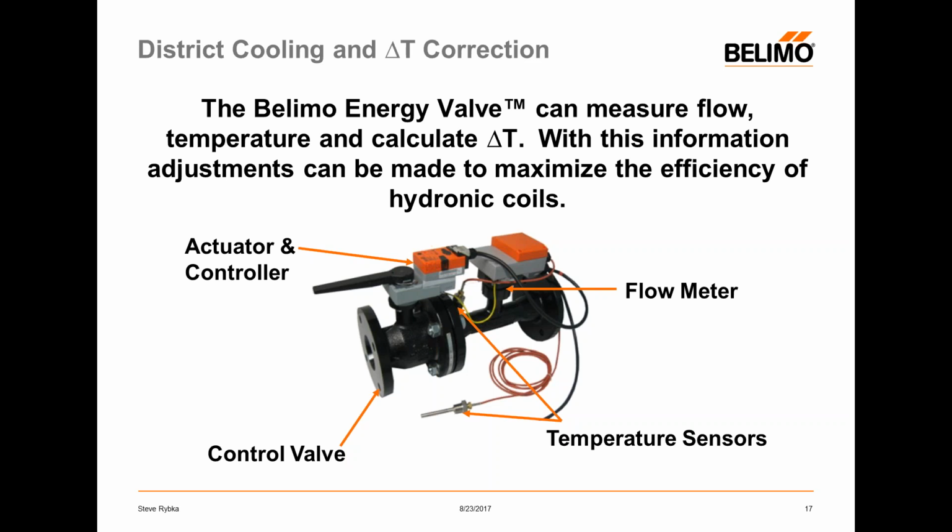So Belimo's been known over the years to make some pretty smart actuators, and we've leveraged that technology to build this thing called the energy valve. And what we can do, again, is measure those flows, measure that temperature, and if we get off our design set point, our contracted set point, or whatever the set point that has been entered into the valve based on the system parameters, the energy valve has a feature called the Delta T Manager.